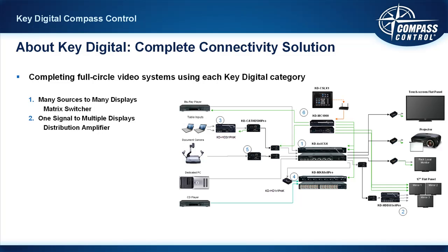A distribution amplifier, which took an incoming video and audio signal and split that signal, for lack of a better term. A single in could go to many displays, so they all view the same thing at any time. And if you are level 1X, 2X, 3X trained, you know that we install these kinds of distribution amplifier systems in very large applications, even retail electronics stores with well over 100 displays, all viewing the same HDMI, HDCP source, not a problem.